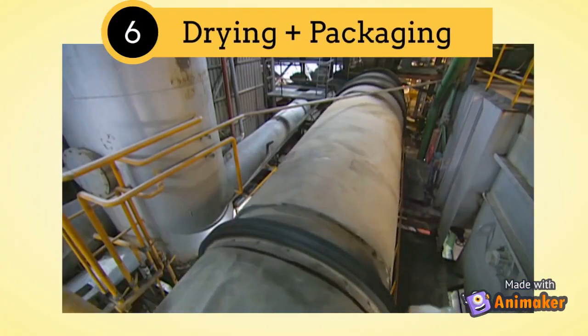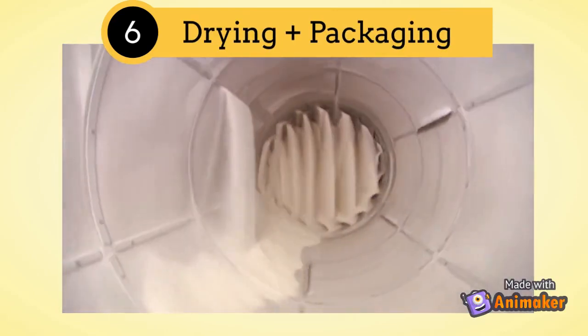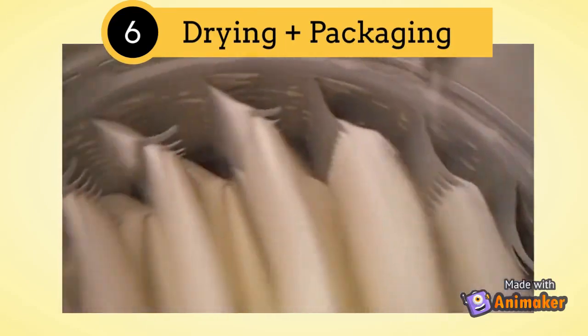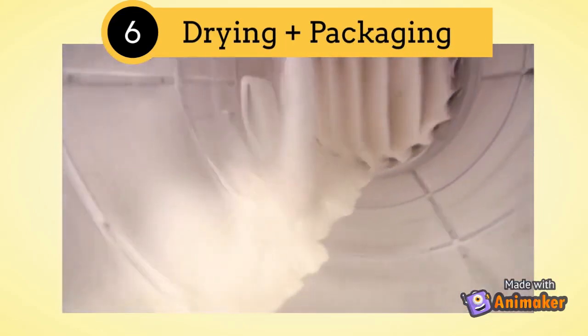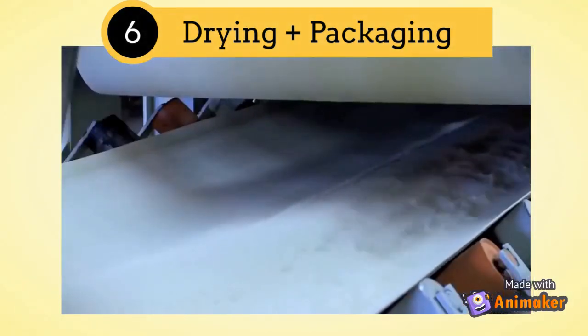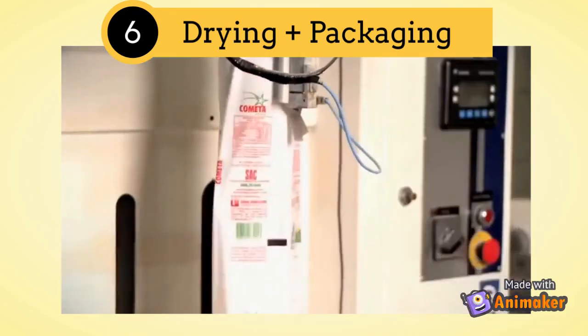The refined sugar still contains about 1% water by weight. Therefore, it is dried by a stream of warm, dry air in a granulator which operates at about 110 degrees Celsius. The dried refined sugar is sorted by size through vibrating screens and sent to conditioning and storage bins.